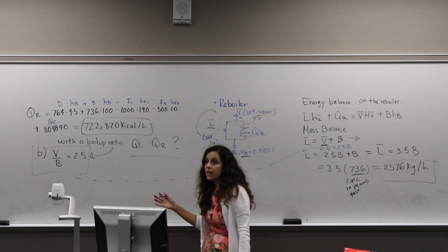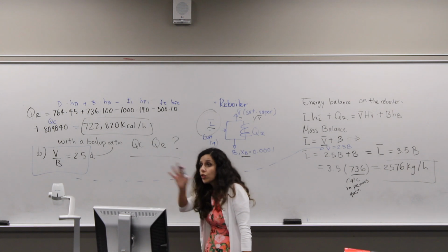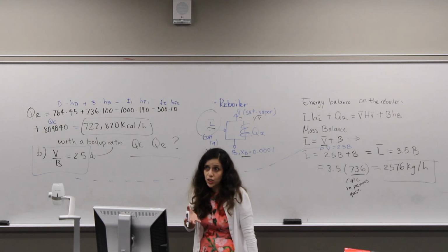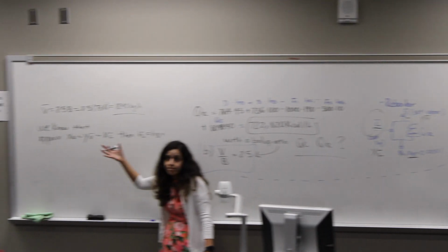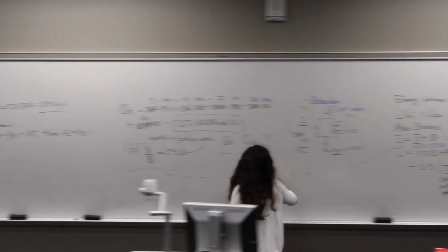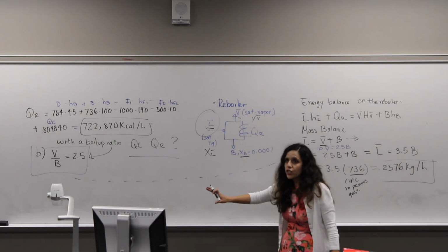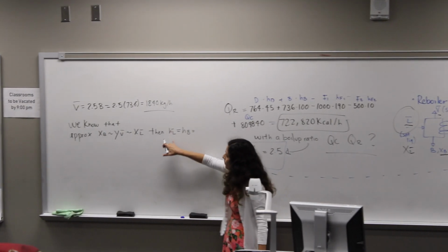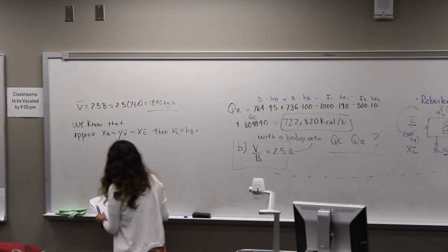So they are approximately the same because we are not doing anything, it's just a reboiler, right? The composition remains the same, it's just a heat transfer process. We are just transferring heat, energy. But the compositions, what happened to them? They're the same. So we can approximate this is equal to this, this is equal to this. That is what I'm doing here. It's just energy transfer, not changing anything in compositions. And that means that I can relate that to the enthalpies, right? So let's write the enthalpy that we might be missing.